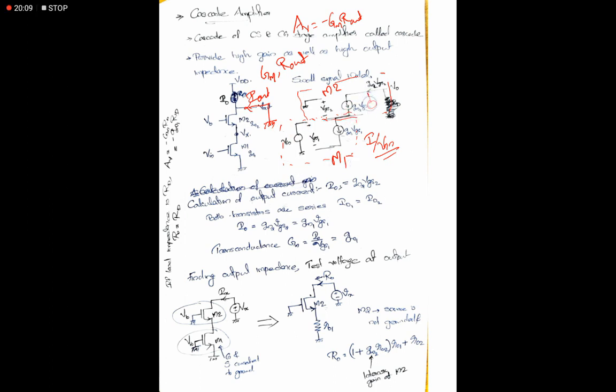If the body effect is there, then gmb2 times Vsb will also be there, and Vsb, if we measure, is equal to the source voltage, across R2. Here I am neglecting this one. So here VGS2 will be there, the bulk is grounded in small signal analysis, and the output is shorted, and we need to find this current.